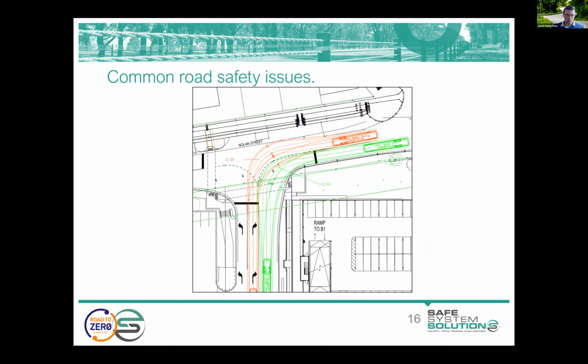Checking some movements on the other side of the intersection, we found that there was quite an issue with overlap of vehicles that would be allowed to turn concurrently under the proposed phasing. So you can see here an overlap in the order of perhaps 2 metres or more. So again, the desirable thing to do would be to widen the intersection to remove these conflicts, potentially amend our phasing if we're able to, subject to capacity and so on, to accommodate these vehicles.